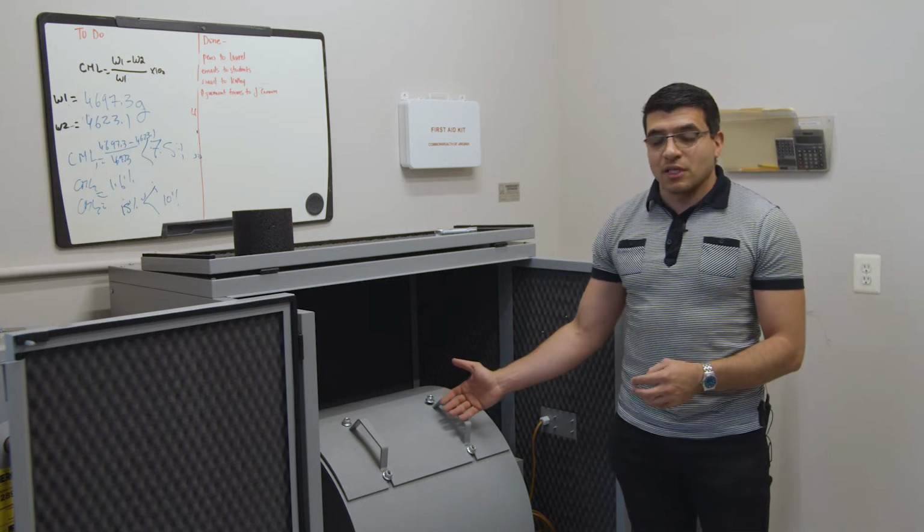Hi there. In this segment, we will show how to perform the Cantabro mass loss test according to AASHTO TP 108. This test method is used to indirectly assess the cohesion, bonding, and effect of traffic abrasion on asphalt mixtures. In terms of apparatus, we need a Los Angeles abrasion machine, we need a chamber, we need an oven,